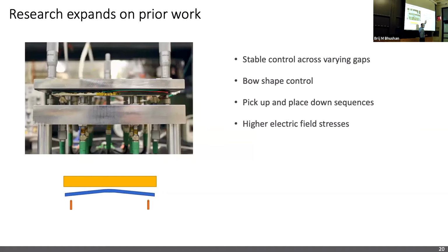An interesting result of this work was that we are able to operate at much higher field stresses than is usually thought possible. In air, normally the dielectric strength that is reported is 3 megavolts per meter, but as I will describe in subsequent slides, we operate for a short duration with up to 11 megavolts per meter without any discharge event. And I think that was quite interesting.